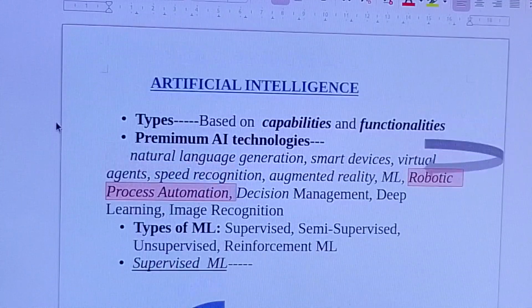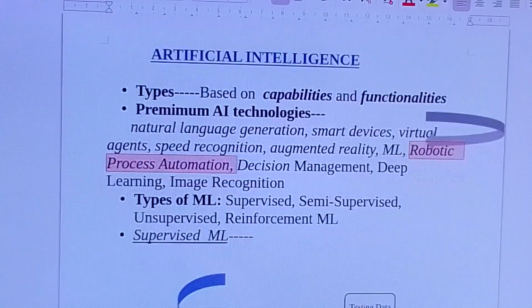Now, lead-through programming. Basically, in this method, the robot is switched to program mode when the operator holds the robot manipulator or its wrist and moves it through a desired path. The robot controller memorizes all the points so generated during playback. The robot manipulator describes the same path as taught during learning, right? Moreover, an editing facility can be provided to compensate for error.